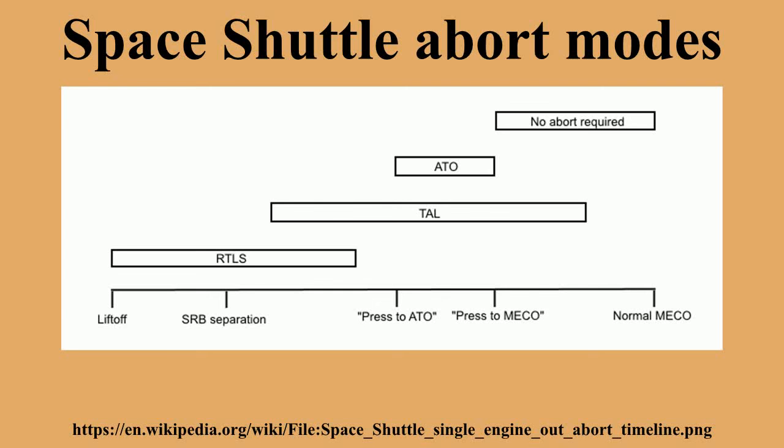Furthermore, the loss of a second SSME during an RTLS abort would have caused an LOCV except for the period of time just prior to MECO, as would a triple SSME failure at any point during an RTLS abort. After the loss of Challenger in STS-51L, numerous abort enhancements were added. With those enhancements, the loss of two SSMEs was now survivable for the crew throughout the entire ascent, and the vehicle could survive and land for large portions of the ascent.